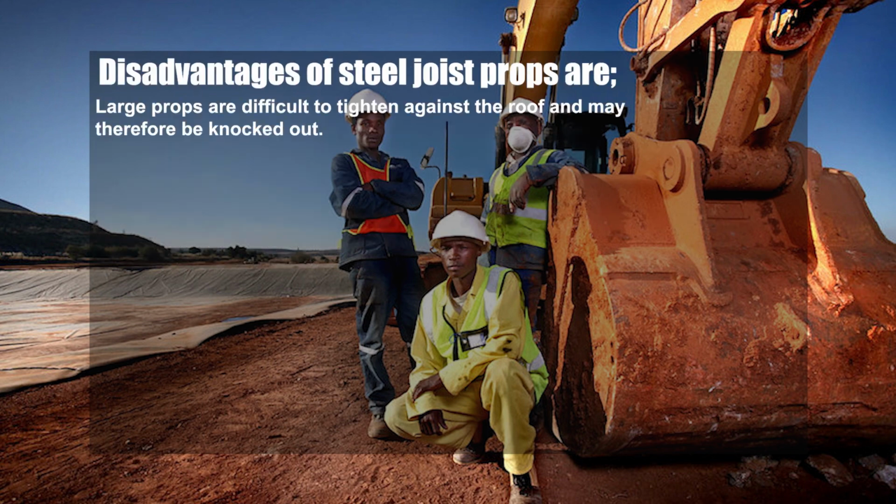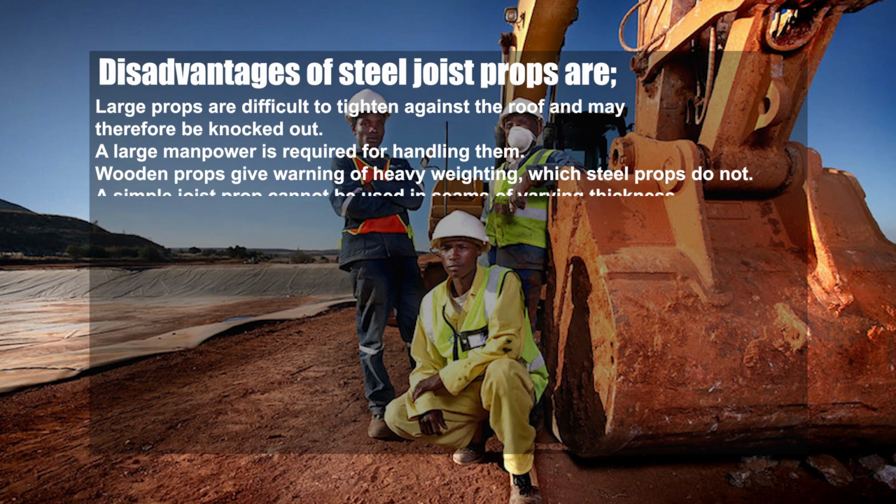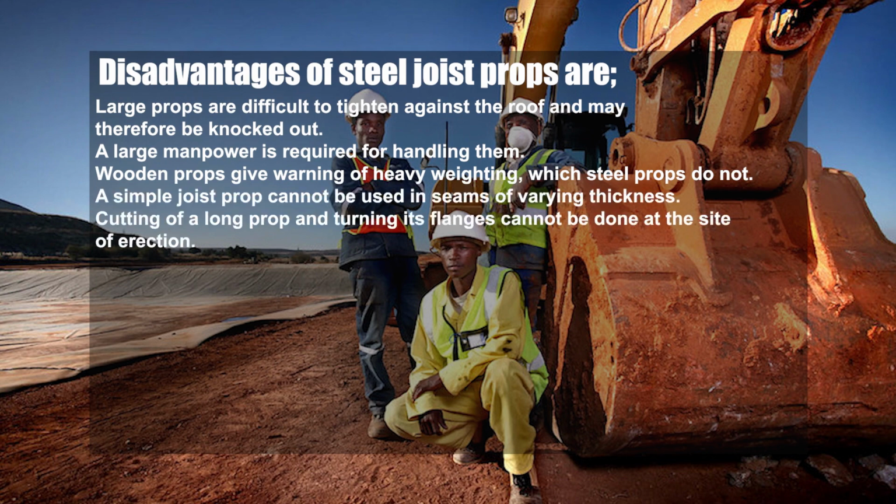Disadvantages of steel joist props are: large props are difficult to tighten against the roof and may therefore be knocked out. A large manpower is required for handling them. Wooden props give warning of heavy weighting which steel props do not. A simple joist prop cannot be used in seams of varying thickness. Cutting of a long prop and turning its flange cannot be done at the site of erection.